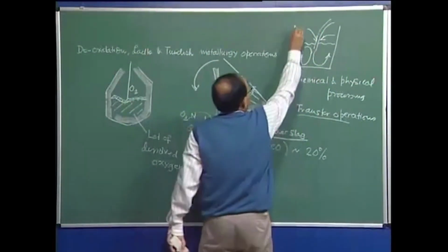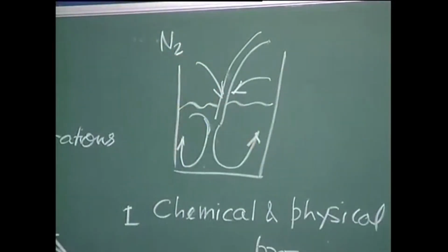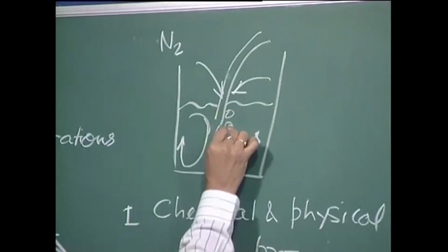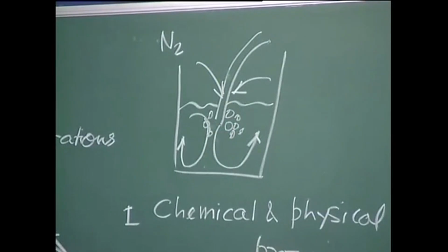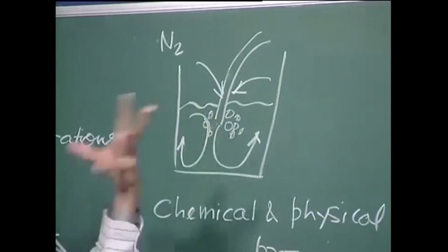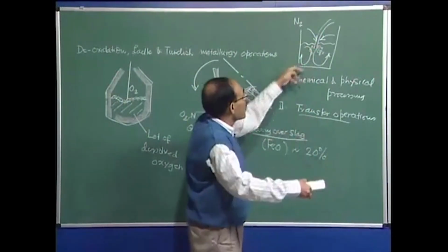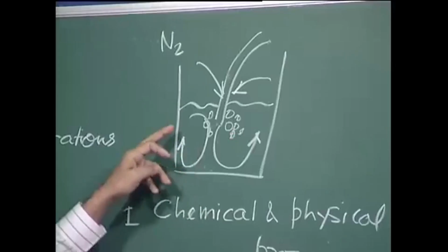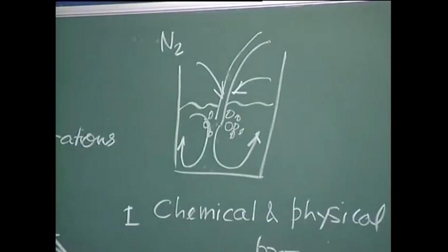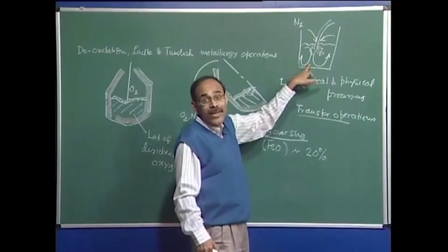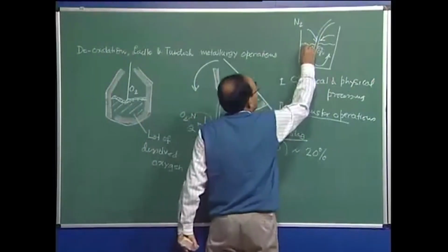On the other hand, you have a lot of nitrogen gas here. We can have some nitrogen and hydrogen which can be absorbed by the tapping stream, and one can see that there is a lot of air entrainment. When this jet, which is an impinging jet, strikes the surface of the ladle, it moves in a counterclockwise direction, and this rotation is at an extremely high speed. So whatever we have added here to make the fresh slag gets dissolved or melted very quickly and instantaneously.